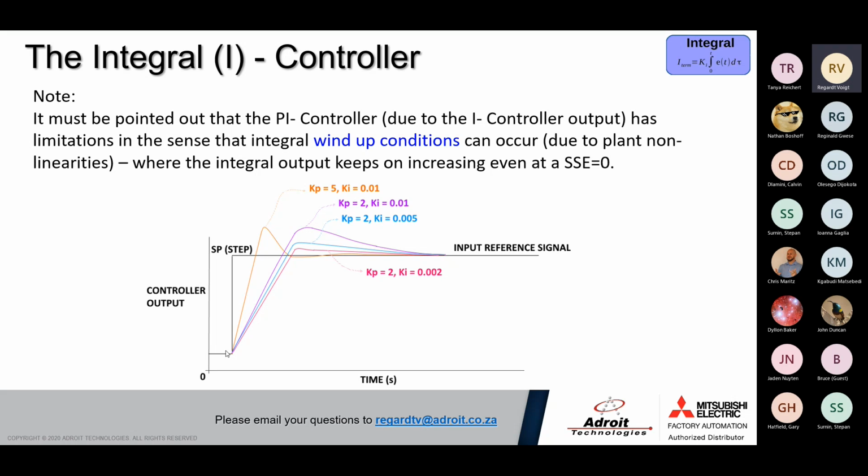the set point. It will just settle underneath the set point value, and then your integral gain will now do the rest to stabilize the signal and to reduce the error to 0, if your integral gain is sufficiently high enough. If it's too low, then it will take some time to reach that 0 error.